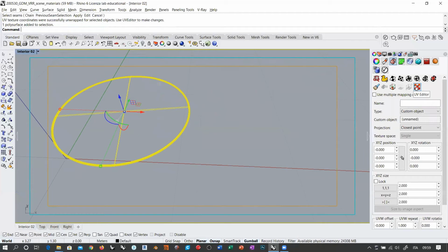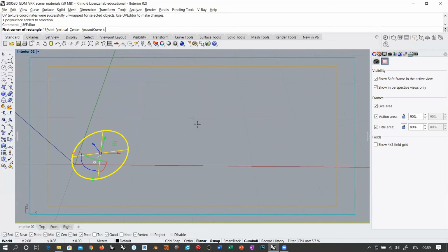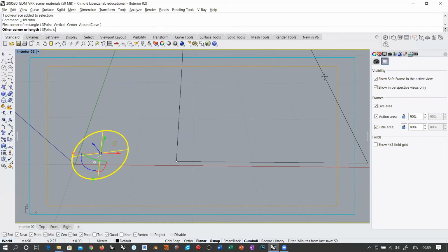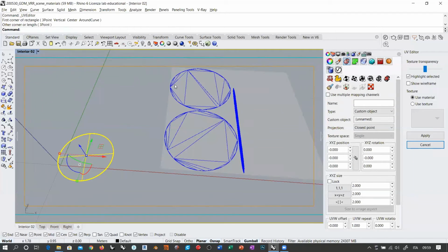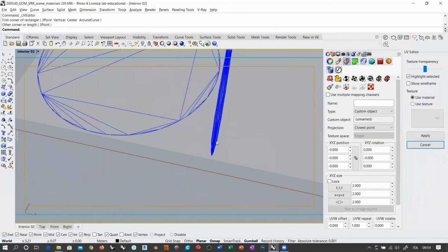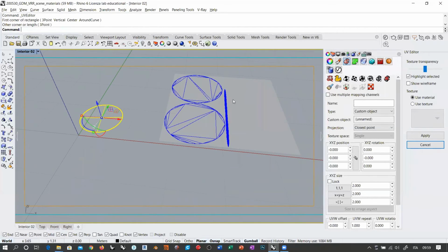Once you have specified the seams of the object, you go to this button, which is the UV editor, and Rhino asks you to draw a rectangle. We are going to discuss this in detail; this is just the general workflow. Let me draw a rectangle here. You see that now we have the unwrap of this object inside the area of the rectangle I just designed. The problem is that the unwrapping is totally messy as regards the side surface of this object, because there are 3 surfaces connected, with some deformation. So we must do something to avoid this kind of overlapping surfaces.